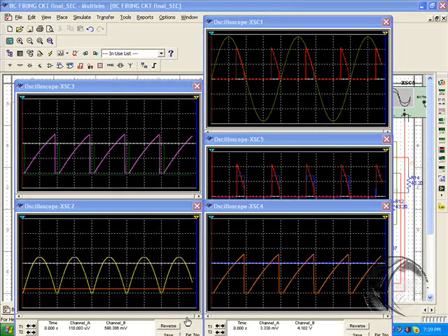Hi, here we will see how we get the pulsating DC, and this pulsating DC is given to a comparator which is compared against this fixed voltage, and that delivers this kind of pulses which are called zero cross pulses or zero detection, zero voltage pulses. This green is the zero voltage pulses, this yellow is the pulsating DC, and this orange is the fixed DC.